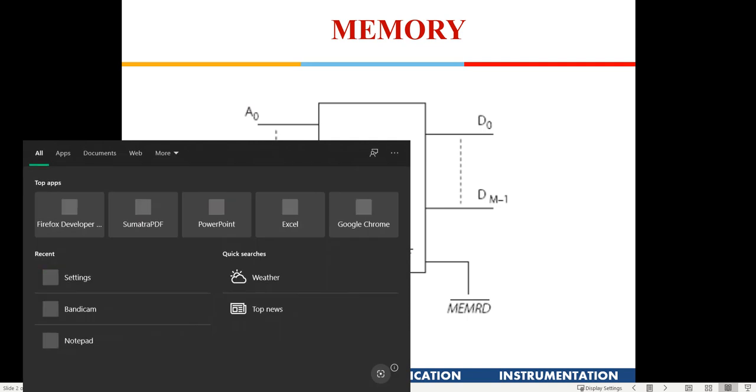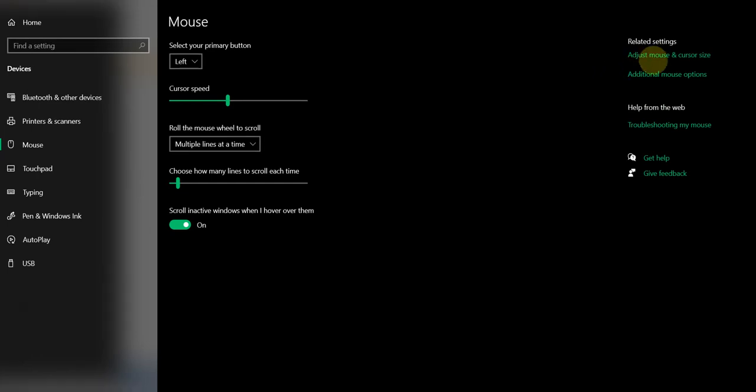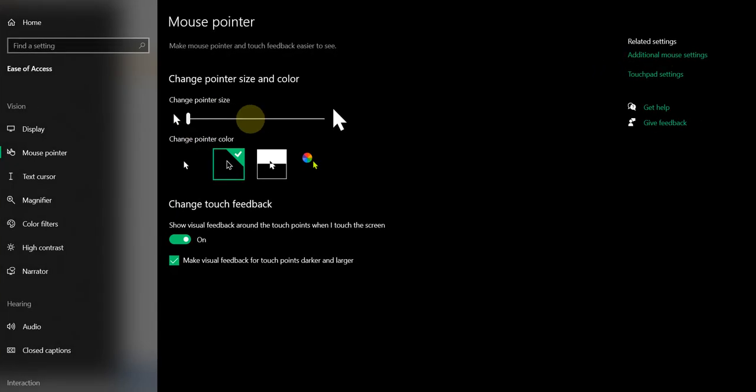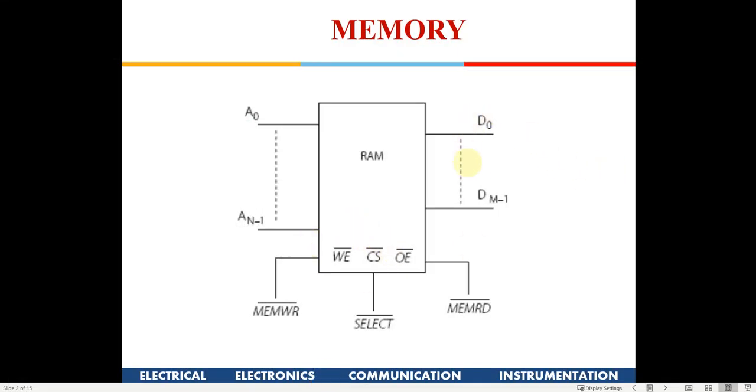When it goes low, whatever data is available on the data line gets stored into the RAM. Similarly, when we want to read data from a RAM, generally we don't directly connect the RAM cell onto the data lines, because the huge capacitances on these buses might corrupt the data which is already written in the RAM. So during read operation, we read it through a sense amplifier.